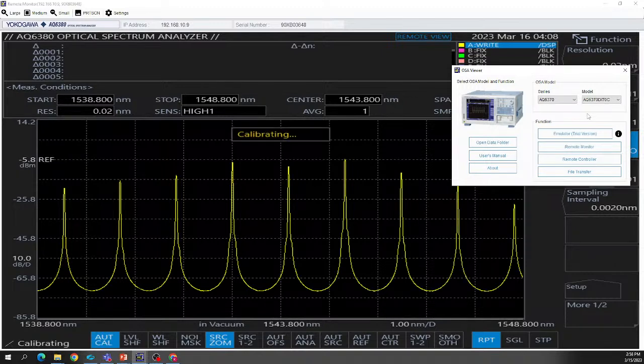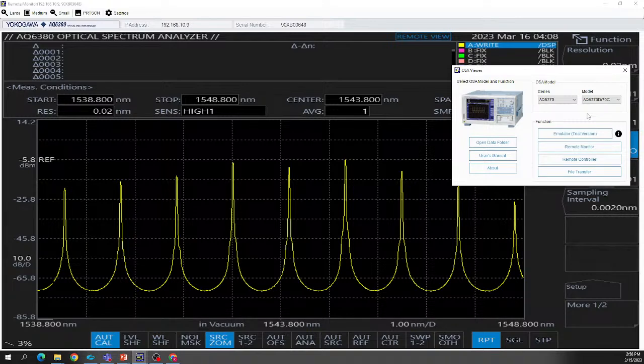As you can see, with increasing the sensitivity, I have essentially decreased that sweep speed, so it takes quite a few seconds more to complete. It's a give and take. It can do very high sensitivities, but at a slower sweep speed. So if you are on a time limit, it would be better to go with lower sensitivities.